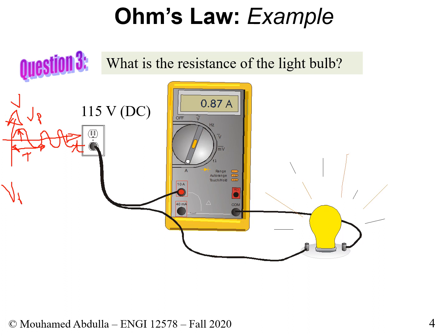So if we check the RMS value of what we have here in North America, typically what you get from the wall is an RMS of 120 volts. What this means is that the peak voltage of North American electric outlets is 170 volts, and 170 divided by square root of 2 gives you roughly 120 volts RMS. So when we say 120 volts, or in this case 115, it's more or less the same. This is really an RMS value. It says that if this alternating current were a DC power, what would this voltage be?